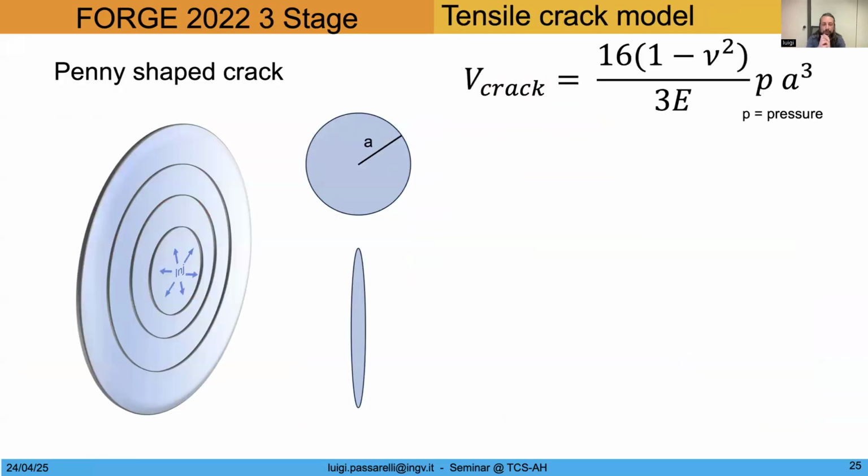And the other, we also introduced a tensile crack model, a very simple penny-shaped crack model. A penny-shaped crack has an analytical expression for the tensile opening of a circular crack. In this case, I'm depicting that you can inject inside, open this tensile crack and then let it expand, shown in side view and in map view here.